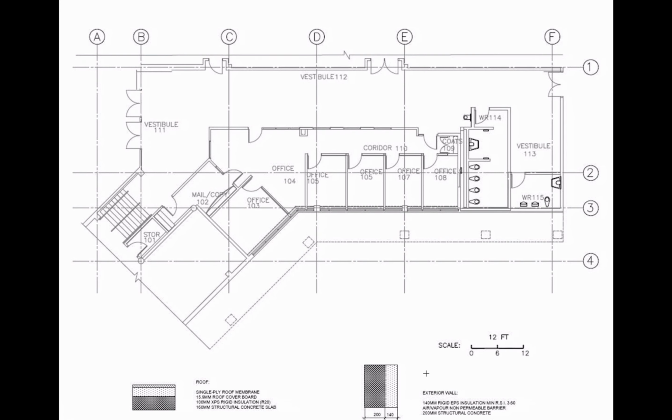To size the HVAC elements, you need to gather a lot of information about each space in the building. You need to study the architectural drawings and measure the length of the walls for each space, count the number of windows, measure the floor area of each space, the roof area of each space, type of occupancy, and understand the envelope structure: the number of layers, type of layer material, and thickness.